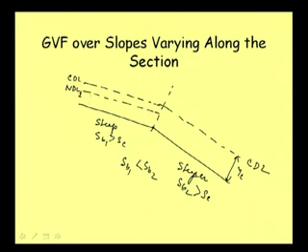This I am writing as NDL1, this is yn1. And at the downstream portion of the channel, as this slope is steeper than this particular slope, the normal depth will be further lower because it is steeper. So we can write that this is yn2, and we can consider that this is going up to infinite extent, and this is also coming from infinite extent.